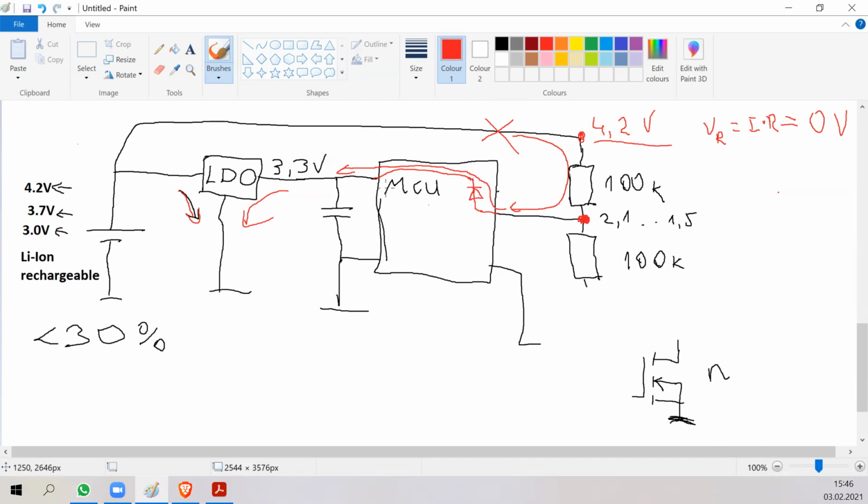Some microcontrollers, for this reason, have removed some of these electrostatic discharge diodes, and then they write that this pin is, for example, 5 volt tolerant. It just means that it doesn't have this ESD protection diode. Since there's no diode, you can connect it up to 5 volts and there will be no leakage current. But the problem is that as soon as somebody accidentally touches the pin with an electrostatically charged finger, maybe an installation person or in a manufacturing plant, accidents happen all the time. So they touch it and the microcontroller is dead.